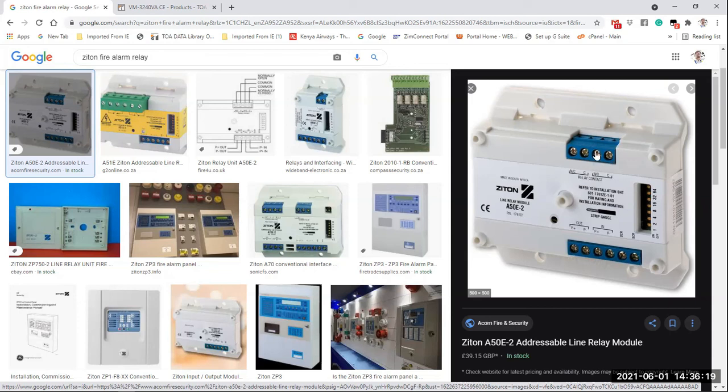And I've said there's no polarity. You can have your orange, white on the common, your orange on the normally open. You can have it opposite. It doesn't matter. There's no polarity. Those two wires are non-polarized. You can connect them anyhow you want.